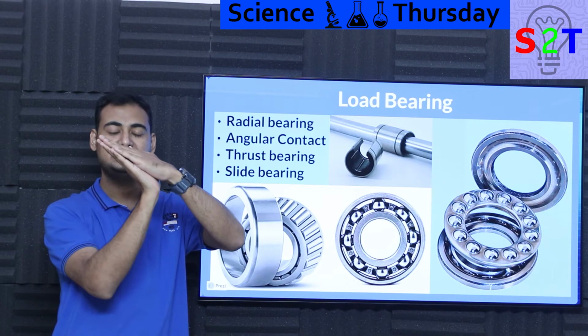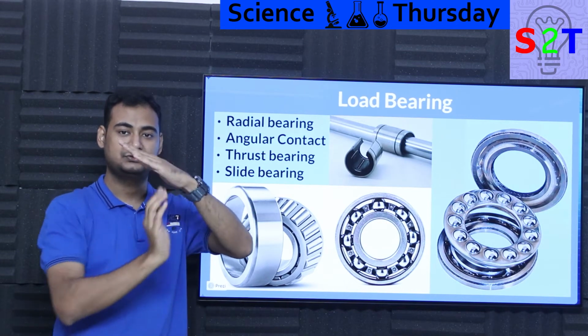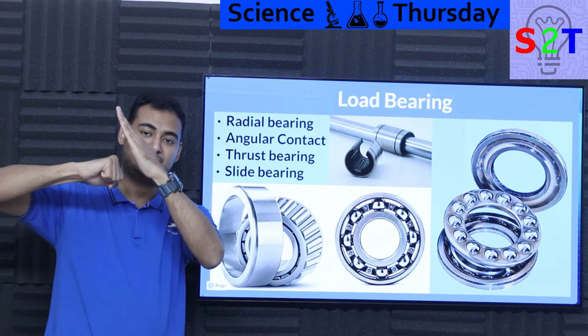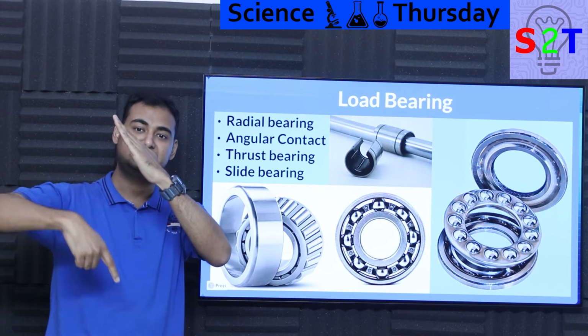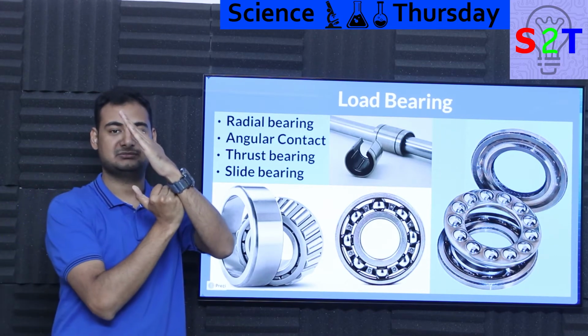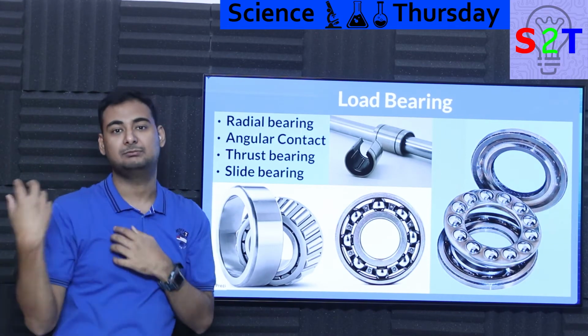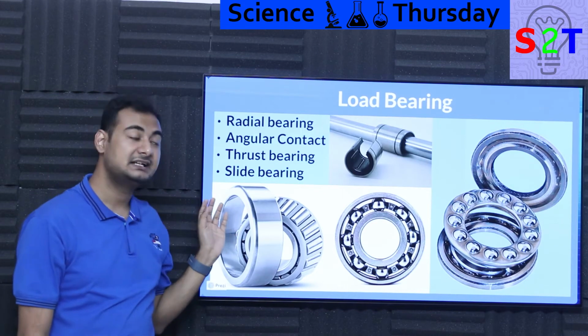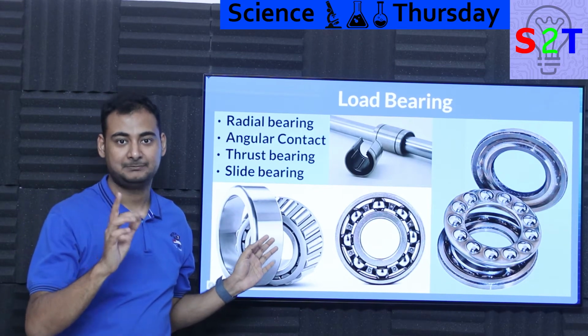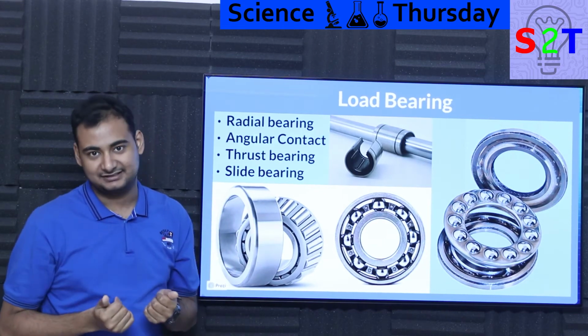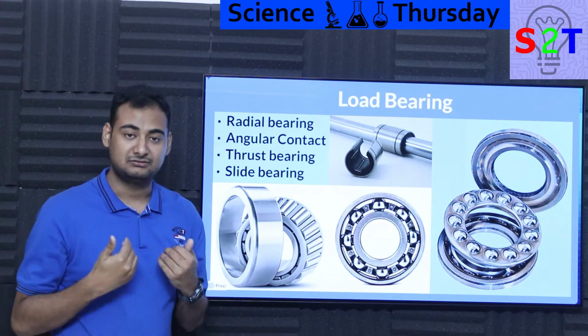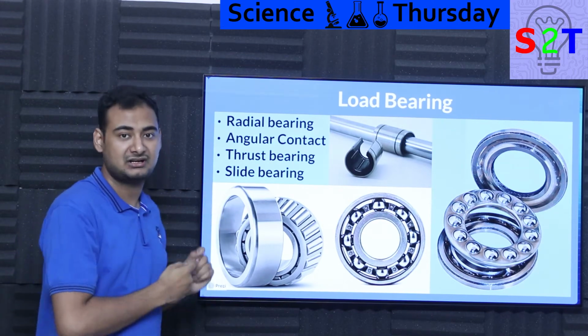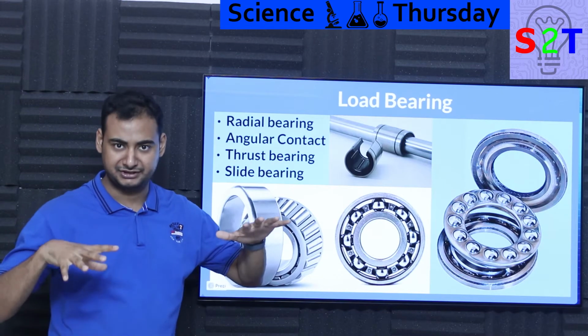Now the benefit of this cone is that you cannot push it through. So if your cone is like this, the action is limited and you can easily spin. Awesome. But here's the side effect. What will happen if you pull it like this? It will pull out. So you will never utilize angular bearings one way. You will always have two facing against each other to lock it. Now what's the benefit of that? Imagine the same truck axle, you have a lot of weight going downward.